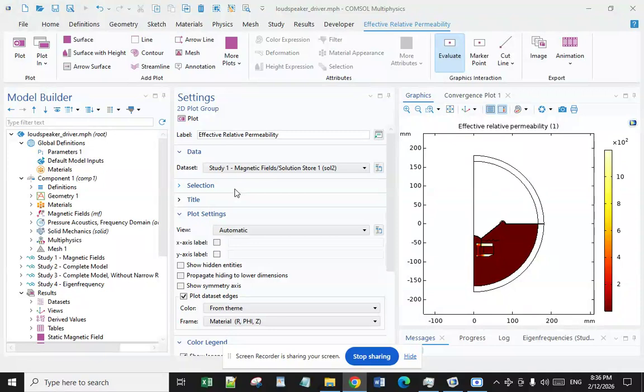The fifth advantage is that it is easier for sensor deployment than using piezoelectric transducers. The wave propagation angle in the test part is affected by Snell's law. As a result, a small variation in sensor deployment may cause a significant change in the refracted angle. The sixth advantage is that it is easier to generate SH-type waves than using piezoelectric transducers. SH wave is difficult to couple to the test part. Electromagnetic acoustic transducers provide a convenient means of generating SH bulk waves and SH guided waves.